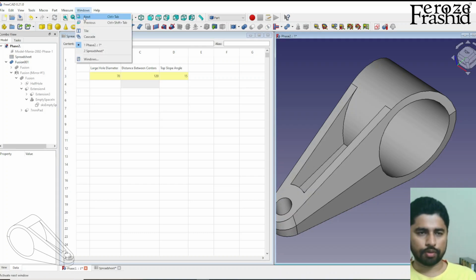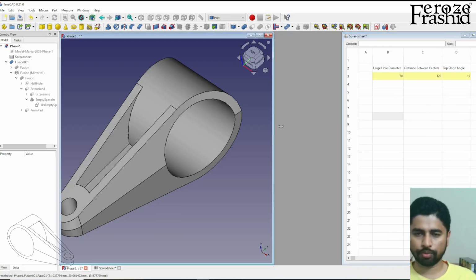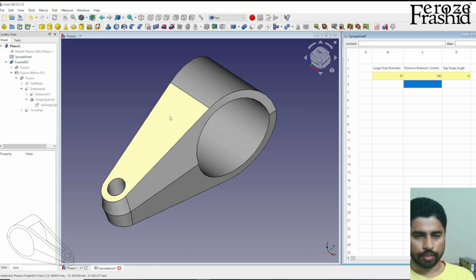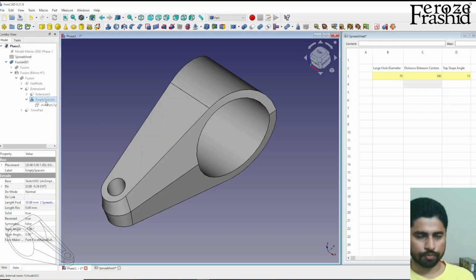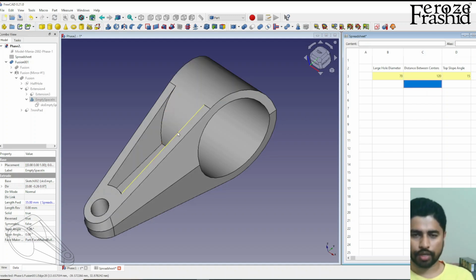So now that we know the problem, let's go ahead and try to pinpoint where this problem is being caused. If I take it to a lower number, we can see the empty space goes away, and that empty space is actually this one. So the inside empty space is not working fine, and we'll have to rebuild that sketch. I already tried a couple times. A couple of my bypass methods have not worked so far.